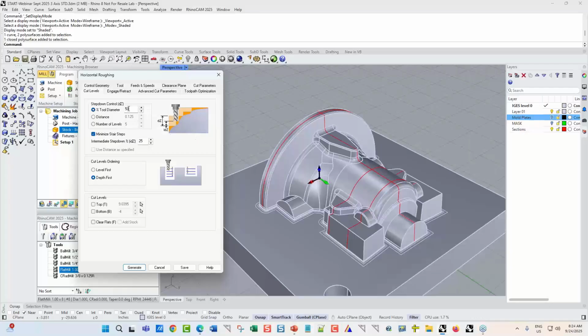So it's going to start cutting at 50%. It's going to go through the entire cut at 50%. Then it's going to come back and cut additional levels at 25% using the same tool. So the first passes will be at a 1/2 inch, and the second step minimization pass will be at a 1/4 inch, 25% of the 1 inch diameter.